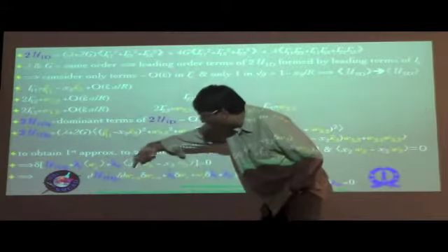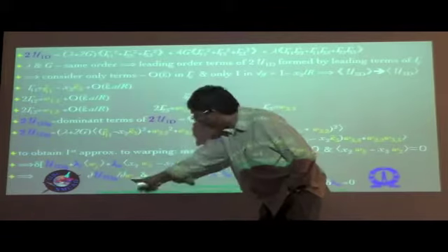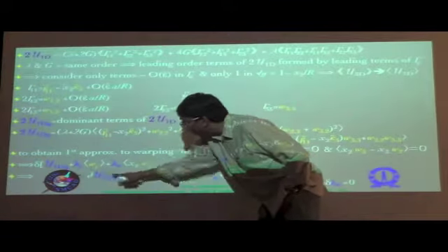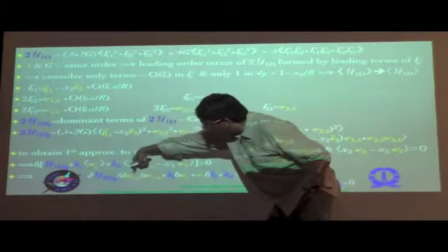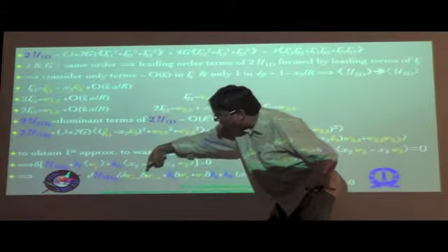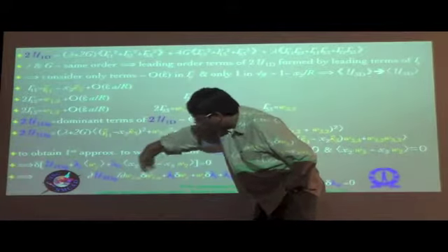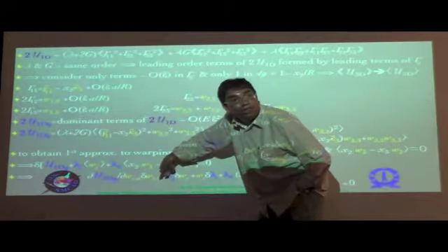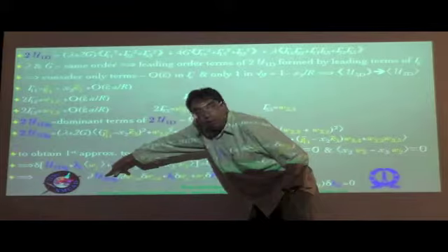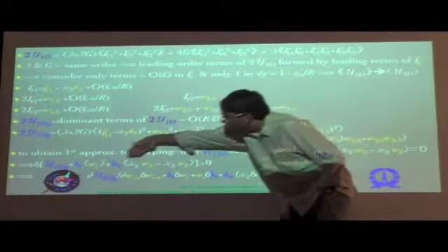So you see that, x2 and x3 we are representing by alpha, the 2 and 3 directions. So it's a partial derivative of U3D naught, which is the integrand of this term alone, with respect to wi comma alpha into the variation of wi comma alpha, right? We'll keep this term aside because here we need integration by parts to remove this derivative in the variation term to be taken to this. So we'll see how that can be done in the next slide. As far as the other terms here are concerned, so here you have this.